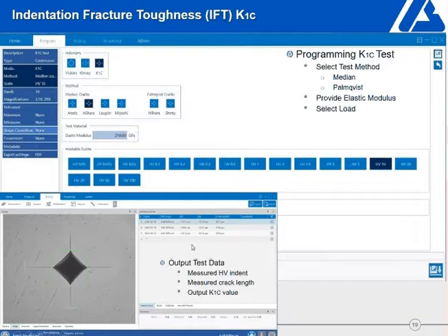which would be, in this case, the D1 average. D2 is an indication of your A value, and the crack length gives you how far it's propagating from the tips onto your material. And this is just a quick way of evaluating indentation fracture toughness. So we've got this incorporated into a software for those of you working on KIC measurements.